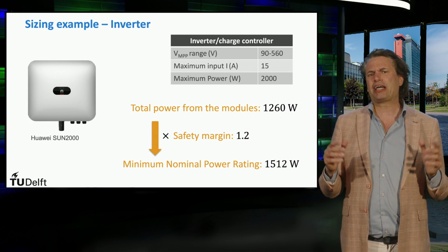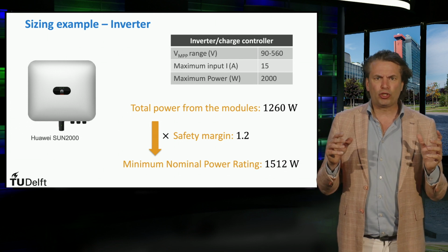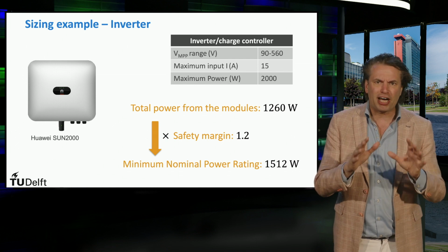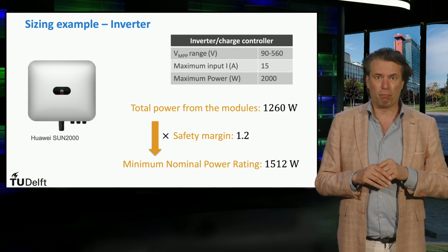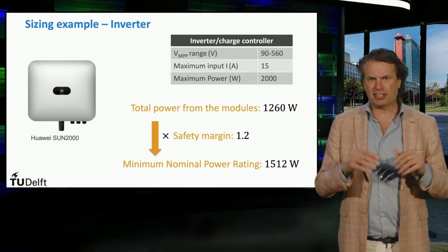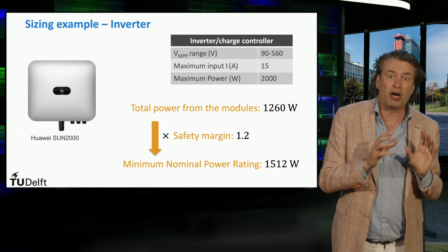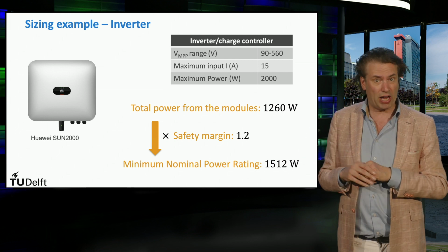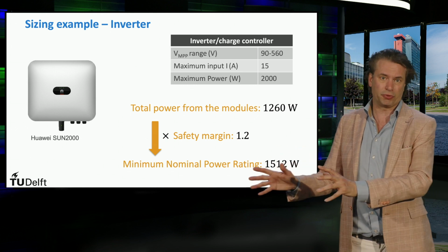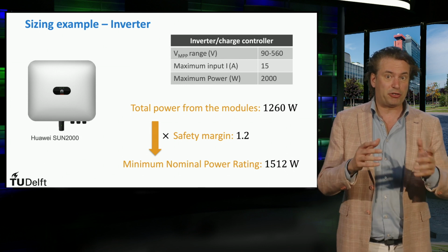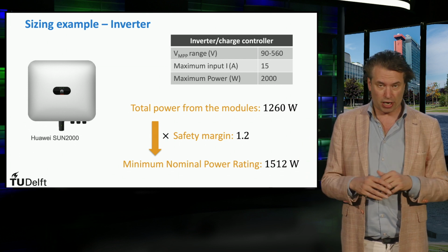As a final note, I would like to talk about oversizing the PV system. Now, should or can a user oversize the PV system even if he can meet the load needs with much lesser power? For instance, in the previous example, what if instead of the 1260 watt peak you had installed 2520 watt peak? Well, in simple terms, it is possible. Any excess you produce is sent to the grid. Whether or not the grid operator pays you back for this excess depends on the net metering related policies of the electric utility you are connected to.